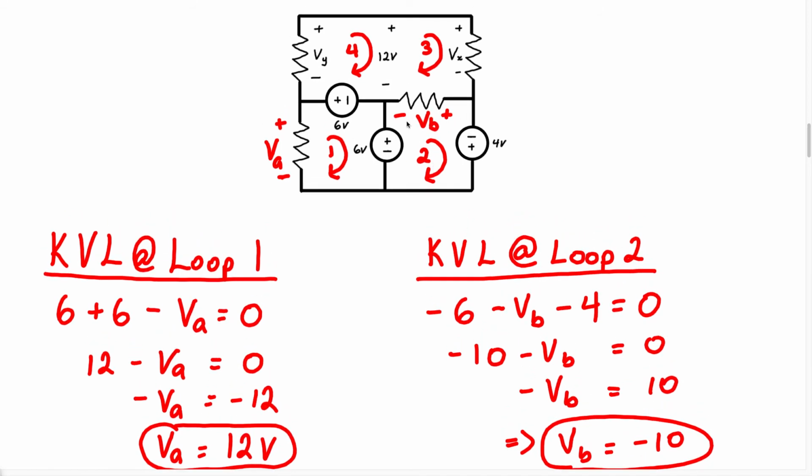Now before we move on, I want to point out something, right? We cannot change the polarity of this voltage. Therefore, we cannot write this as minus plus. It won't work that way. Once we draw in a voltage and we have its polarity, that is going to have to stay constant throughout this entire problem. We cannot say now that this is minus plus, because that's going to throw our passive sign convention all the way off, okay? So once you have something, you stick with it and you keep it going. Everything is going to work out in the end, right?